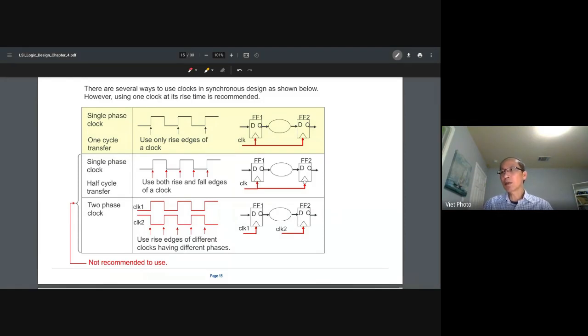It's not as simple as writing an AND gate and a NOR gate. What the RTL code describes is the function. It's quite like pseudocode, like a plus b, or if you have c equal to a multiplied by b, that's a multiplier. The multiplier is a big macro, right? In that, they will have a lot of adders, shifters, and so on to realize the function of multiplication. So the bottom line is the guys who write the RTL don't know much about the real life of the flop.